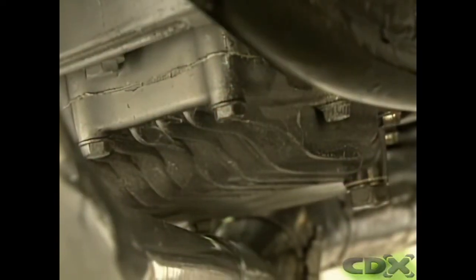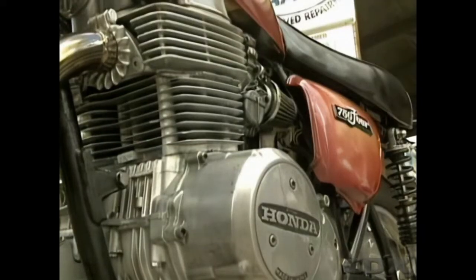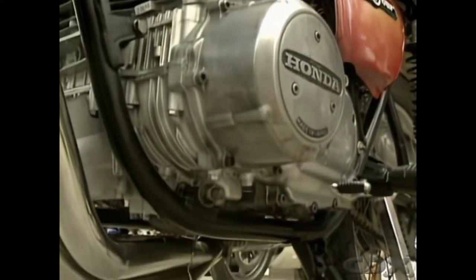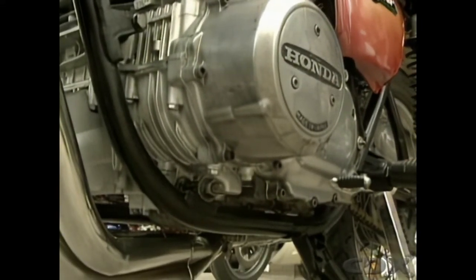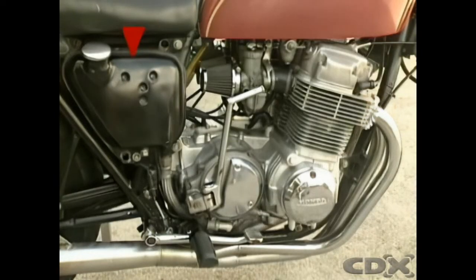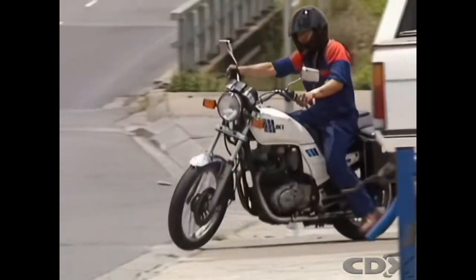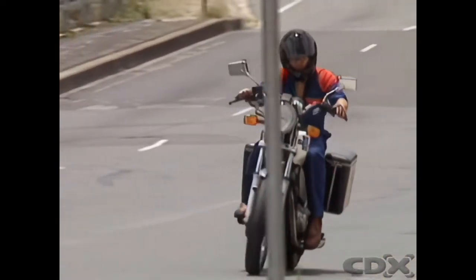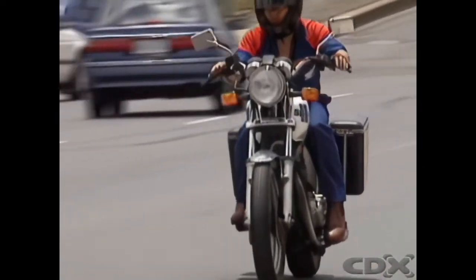Because there is no oil storage sump, the engine can be mounted much lower than in a wet sump system. The oil tank can be positioned away from the engine where it can get best cooling, and the amount of oil in the system can be much greater than in the wet sump system.